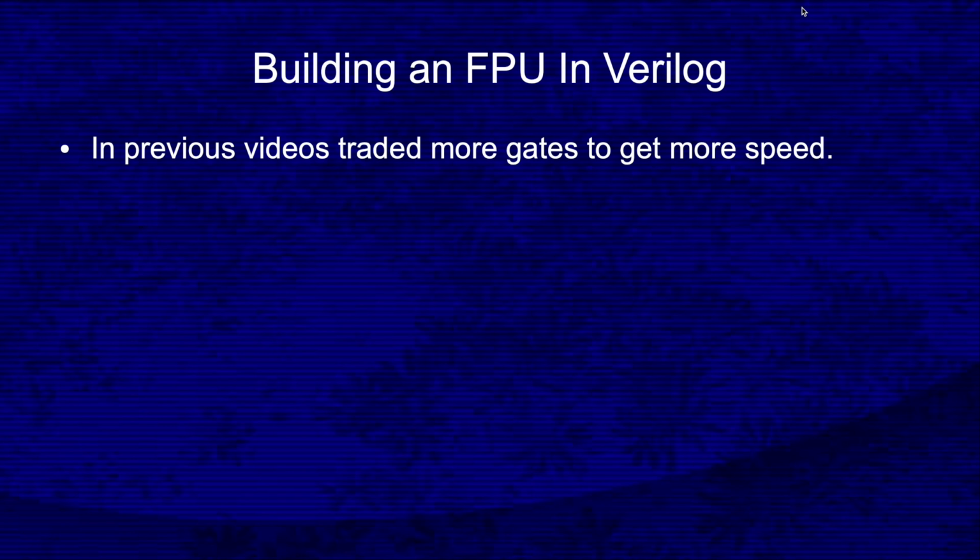My goal in designing an FPU is to figure out how to make it as fast as possible. You might remember from my earlier series on optimizing the performance of the circuit which multiplies the 2 significands that each time I improved the performance of the circuit, I did so at the cost of more gates. There are situations where speed isn't the most important factor. Conservation of chip real estate might be more important in some applications.